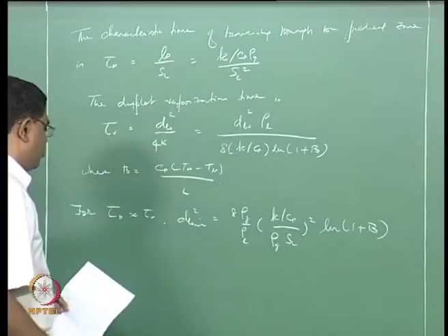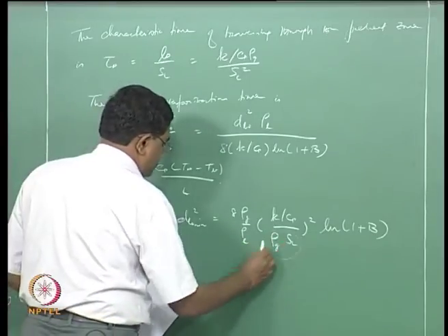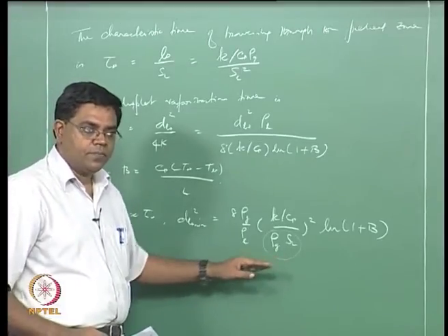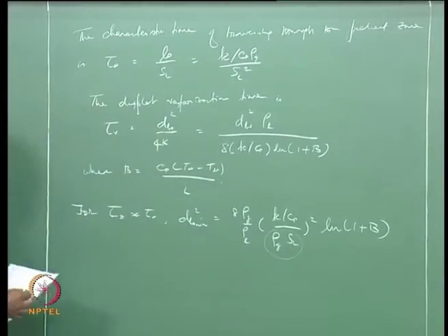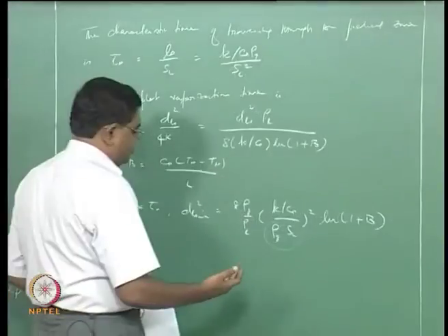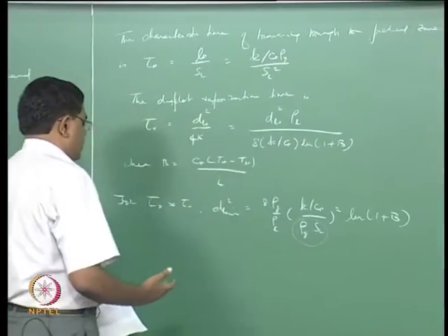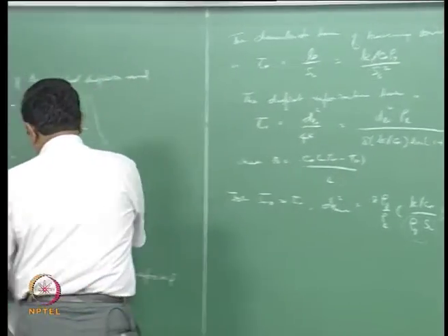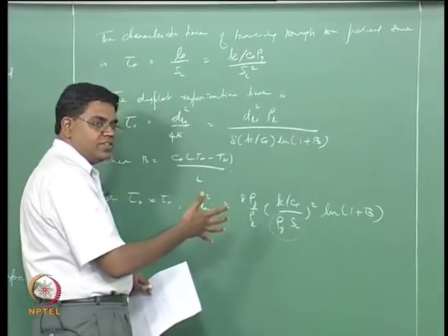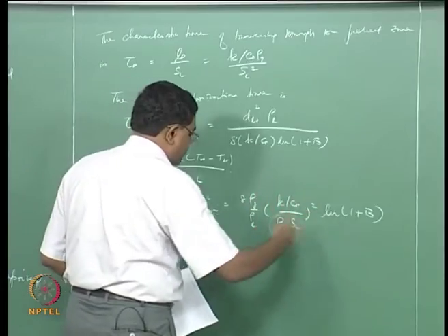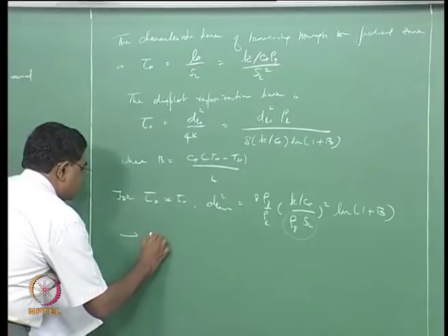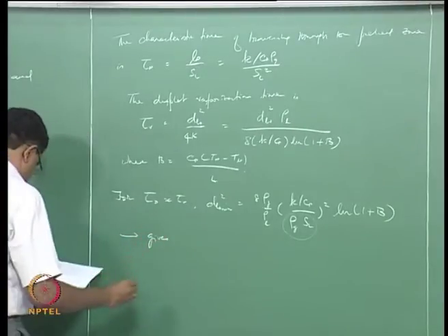The reason why we write rho g SL together is that this is actually the mass burning rate, or the burning mass flux. Okay, so now for typical values, if you assume an approximately stoichiometric mixture of fuel and air where the combustion happens, and then you throw in rho L over rho G being of the order of 1000, and so on, you do all these things, and this gives about 10 microns.